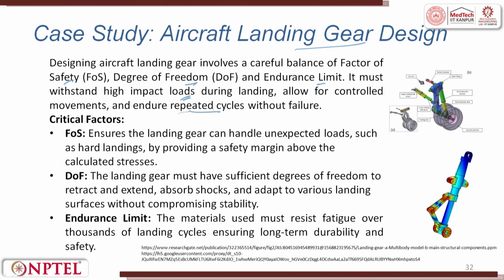Once you put a landing gear, there might be 1000 takeoffs and landings. So, it endures repetitive cycling without failure. The FOS ensures the landing gear can handle unexpected loads such as a hard landing by providing a safety margin above the calculated stress. For the degrees of freedom, the landing gear must have sufficient degrees of freedom to retract and extend.